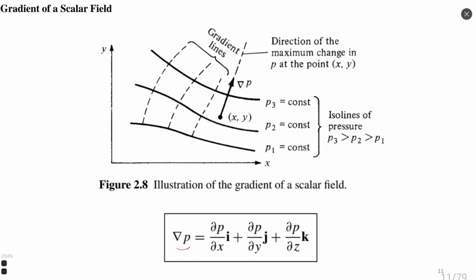When we would like to see the gradient of this parameter, like pressure gradient, for example, we know that it's always perpendicular to constant lines. For example, if I would like to see the pressure gradient at some arbitrary point, I need to make a line perpendicular to the isoline, and I can see where the gradient of pressure goes in each particular point, always perpendicular. I hope my lines are perpendicular, so let's assume they are. Isolines have direction always perpendicular to gradient lines. Unfortunately, I think Fluent does not show gradient lines, but we can always do such visualization when we process results of simulation.